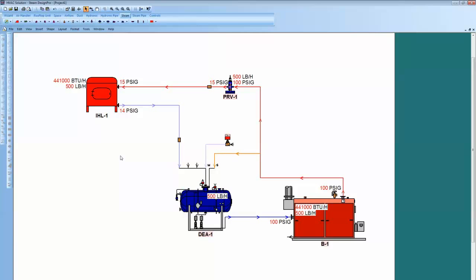The third major item, you have to have some load, some utilization, process load. This a lot of times consists of coils and heat exchangers. And then last of all, you need to have some condensate recovery method. How do I get the condensate back to the boiler? Deaerator, boiler feed pump, condensate pump would work on that.